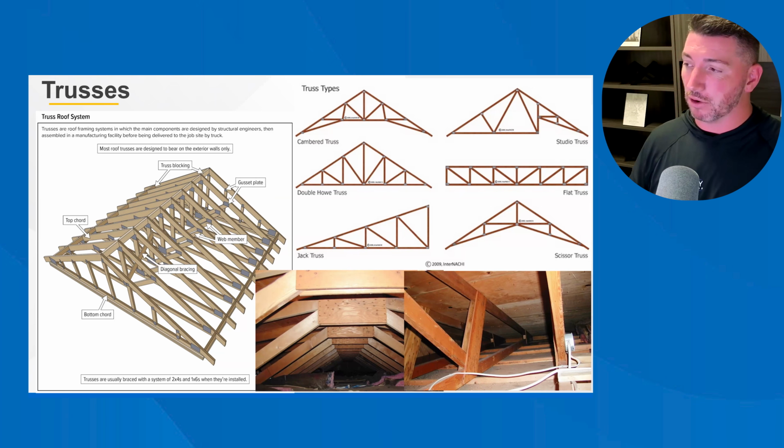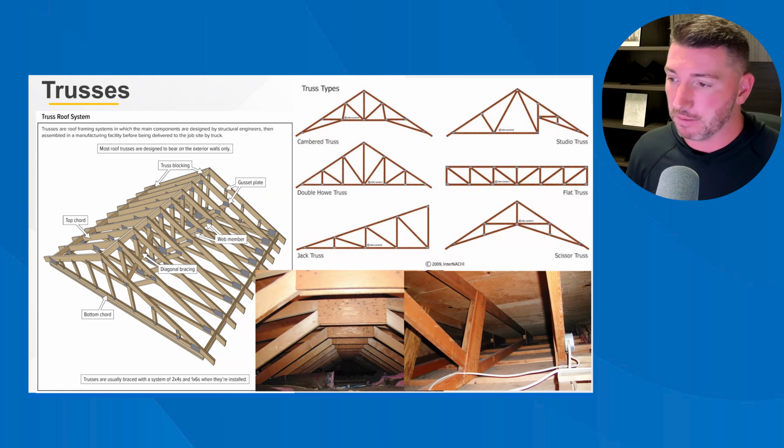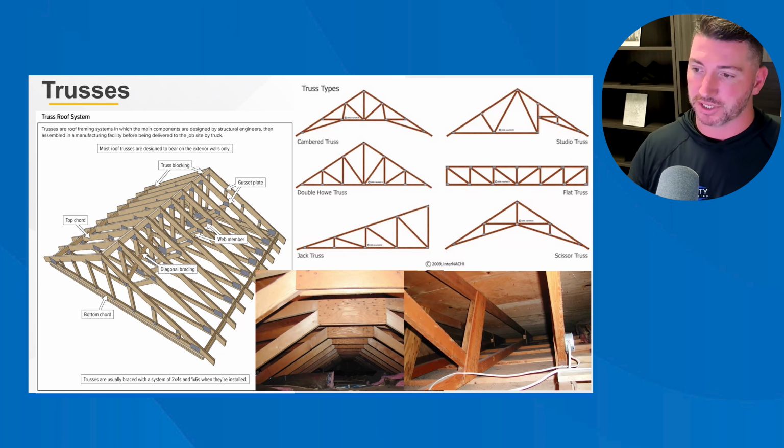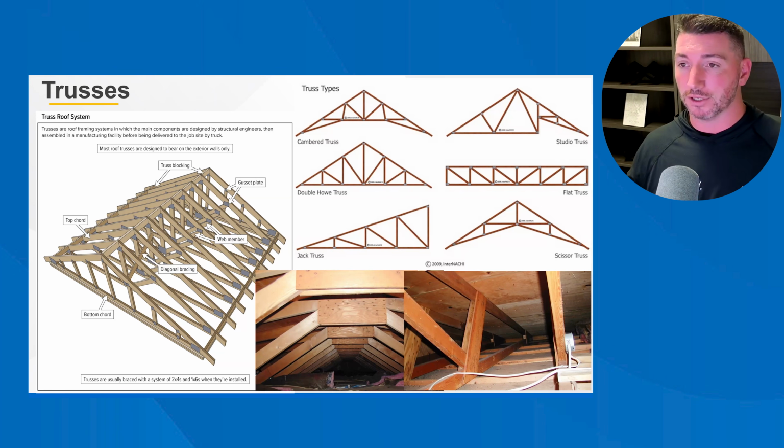Look to see if there's metal plates attaching these different framing members. And the main thing for you guys, if you're looking in the attic and you see a truss system, look around at the other components. Look for electrical, look for HVAC, look for these other things because a lot of times those contractors have zero structural knowledge. They have zero code knowledge about structural members. All they know is their trade.